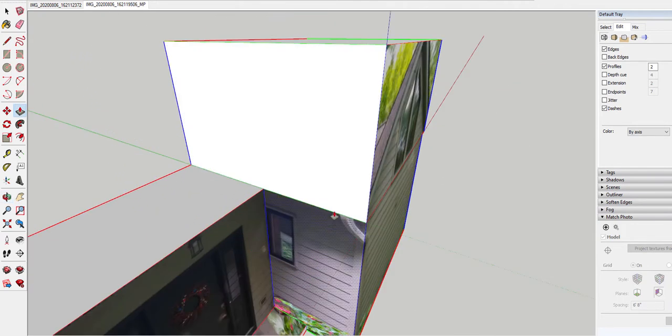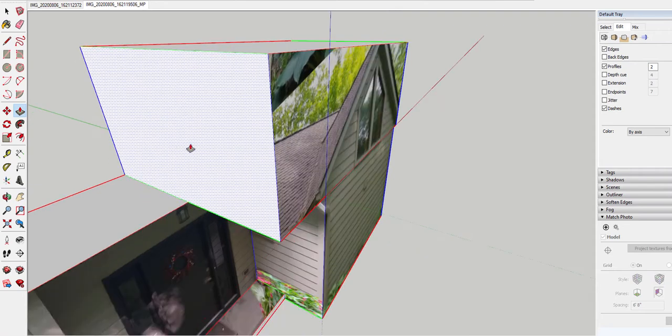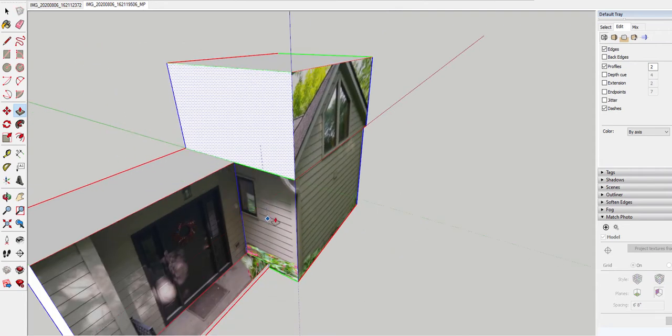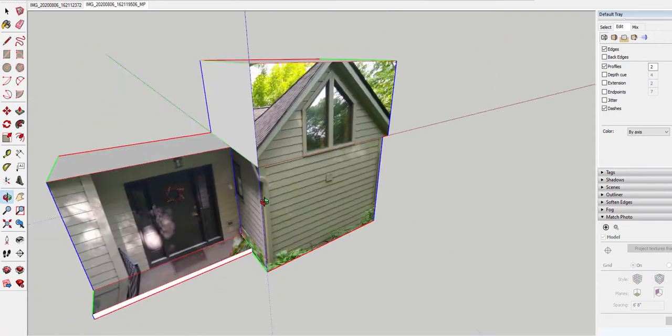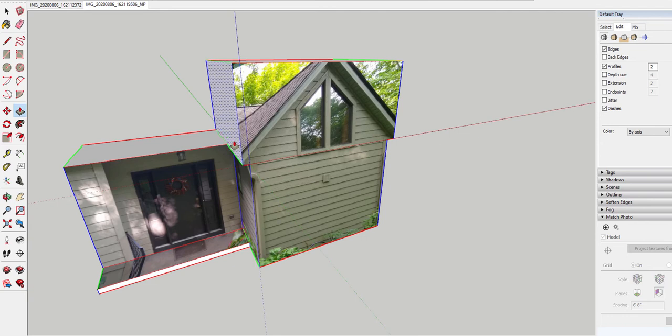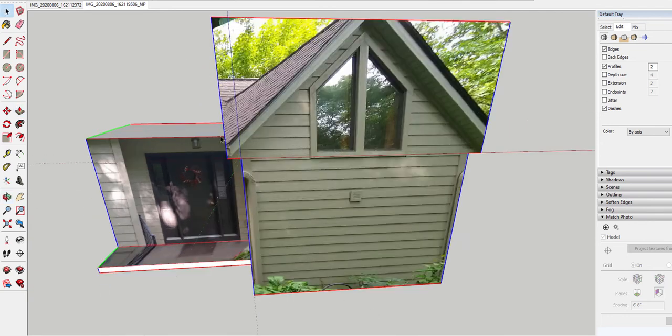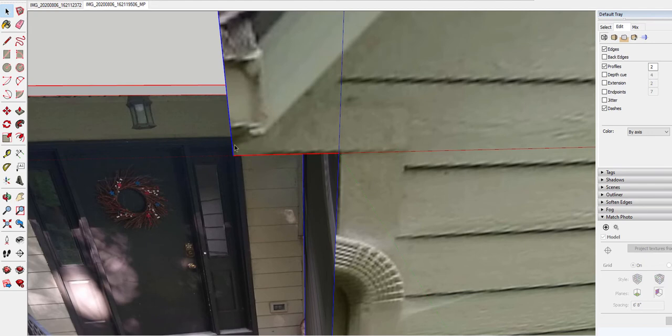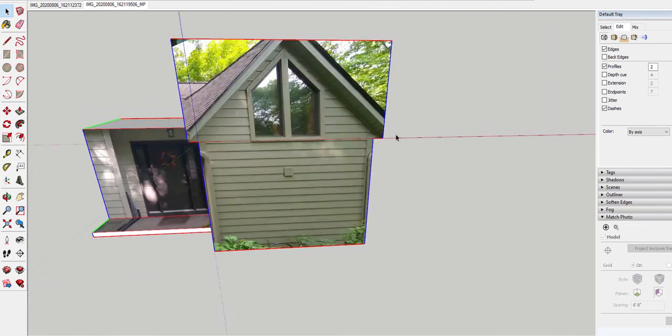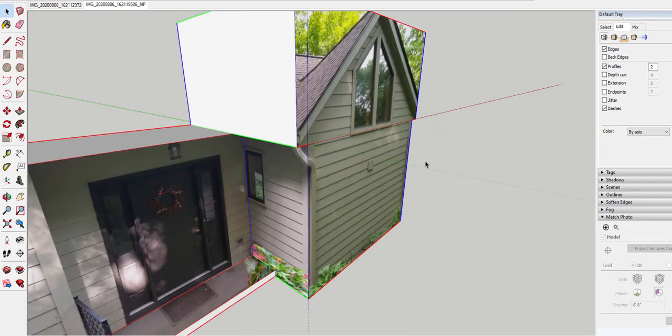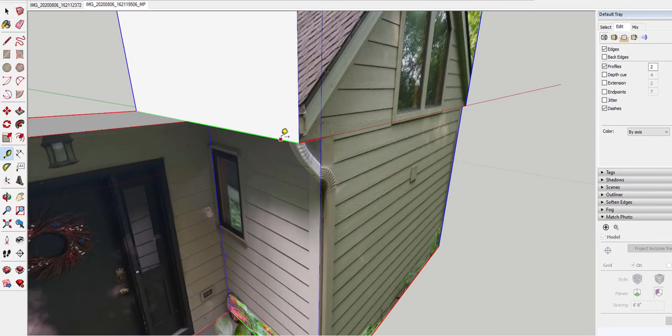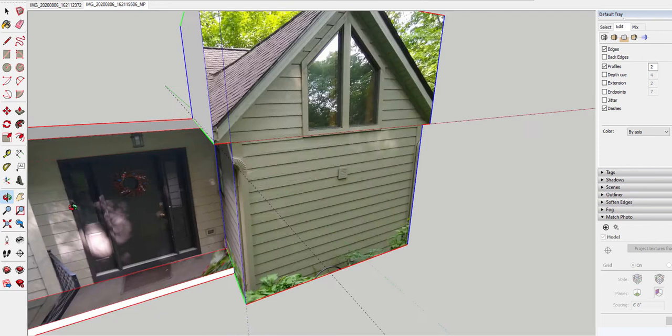So I'm lining it up. I'm clicking on the surface, click, and then clicking on this surface here to line up. And then I'm going to go out 9 inches. So both are out 9 inches. Now it looks to me like there's a little straight portion before it goes to the gutter. So let's see, if I go up in the straight portion, maybe about 2 inches, give it a take.